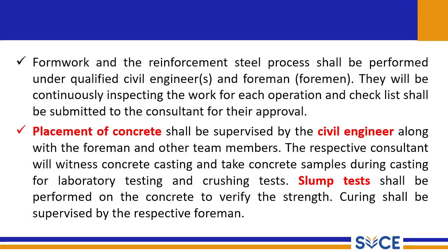So these are different quality tests that we do for concrete. When placing concrete, we are going to take some concrete samples, that is, cube samples, for laboratory testing or crushing for compressive strength of the concrete. So we can do such tests to ensure that the quality characteristics are achieved. For concrete, we can say it is the compressive strength: whether the required compressive strength has been achieved or not, that we can check while placing the concrete.